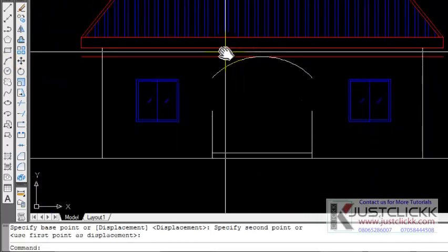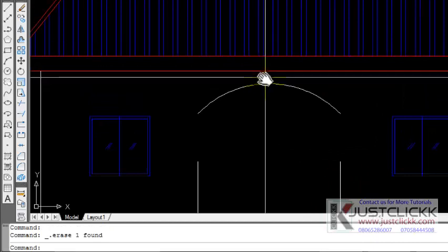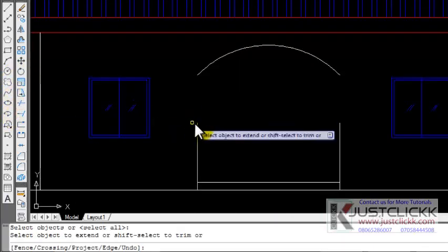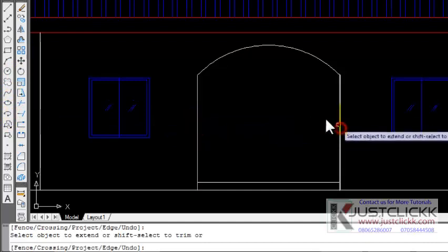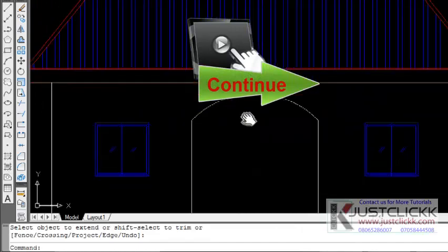Then you delete this fascia board line you just offset. Now this is to scale, which is the good thing you want. So let's now extend this line to connect with that. So this is how you can create such things, modify them, play around with them.